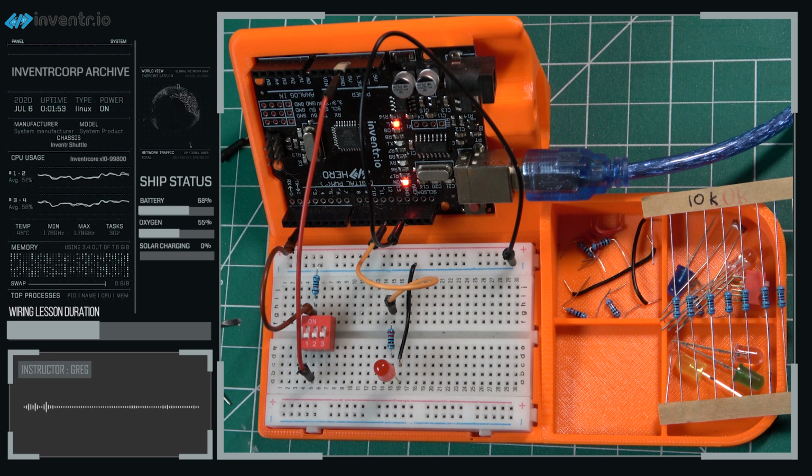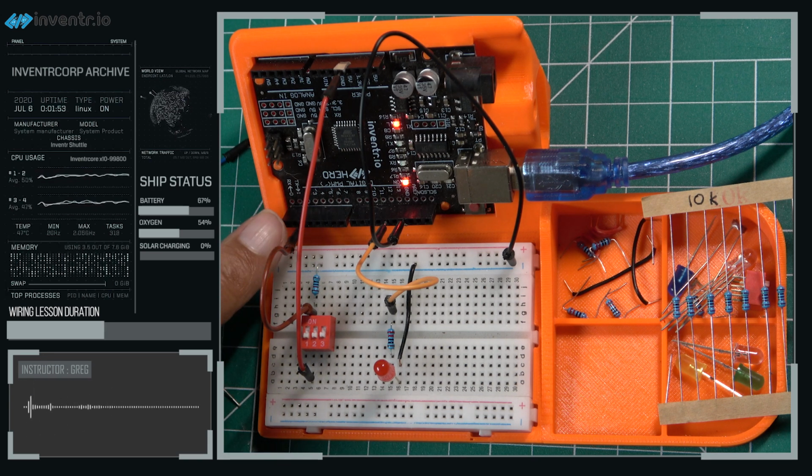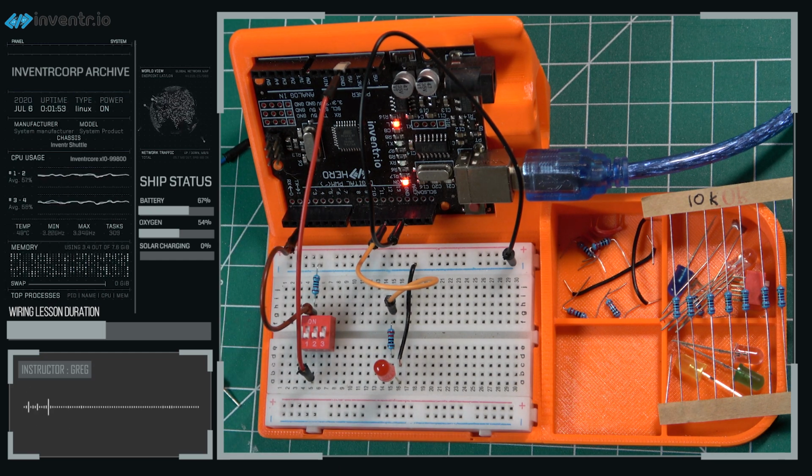And in that condition, pin 2, connected by this brown wire to this point in the circuit, would read a low. So this is how, by flipping the switch between on and off, we can toggle the voltage at pin 2 between being high and low.